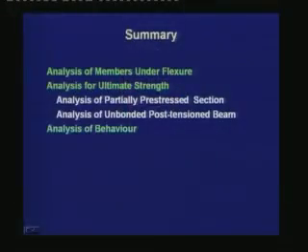We also studied the analysis of unbonded post-tension beams, and we learned that for unbonded post-tension beams, we cannot use the strain compatibility equation as we have used for bonded beams. For an unbonded post-tension beam, the compatibility is based on overall deformation. Thus, it needs an integration of the strain in the concrete at the level of the CGS. The code allows us to use simplified expressions of the depth of the neutral axis and the force in the tendons from the tabulated results.